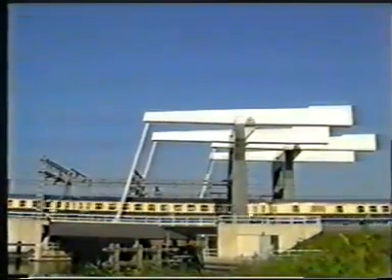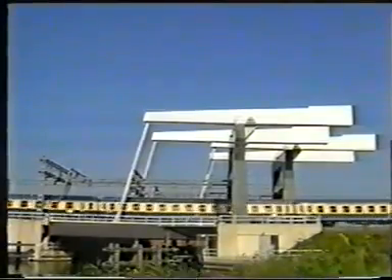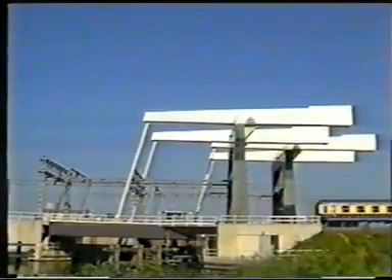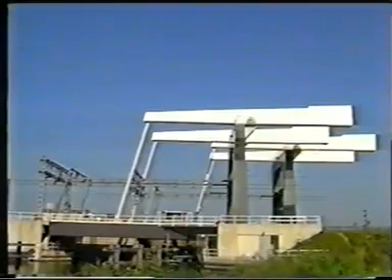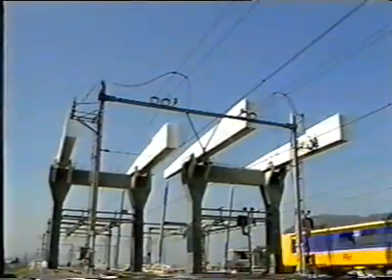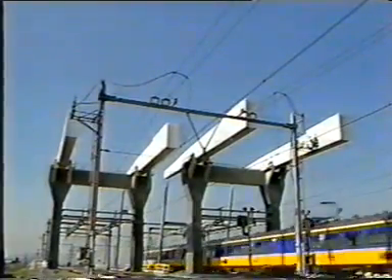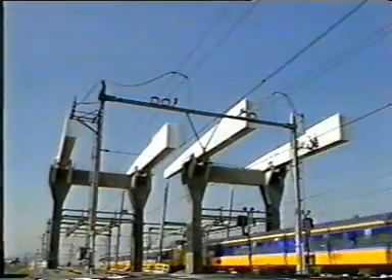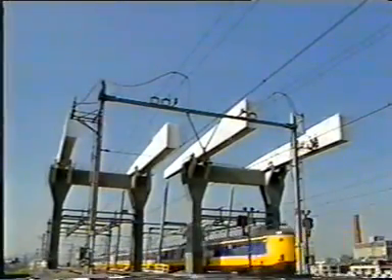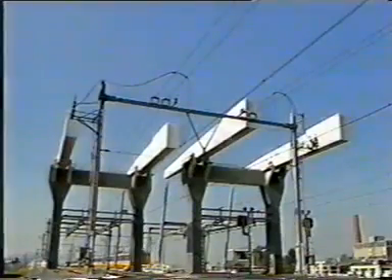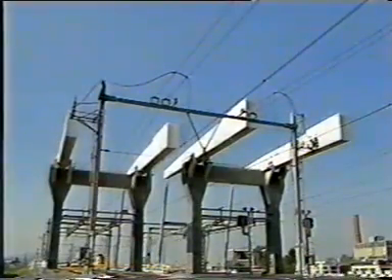A bascule bridge with overhead counterweight. The structure consists of the movable deck, the tie rods and the balance frame, including the counterweight. The balance frame is supported, in this case, by a portal frame. In this railway bridge, the bracing between the balance beams is missing.